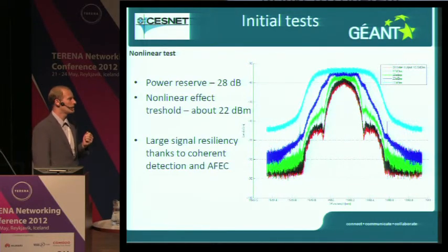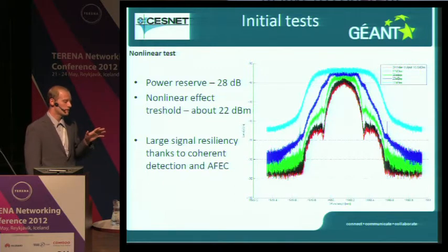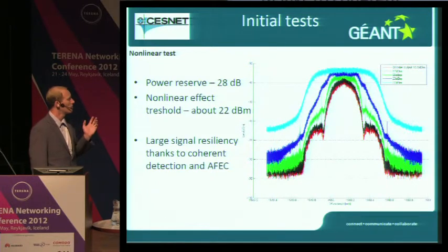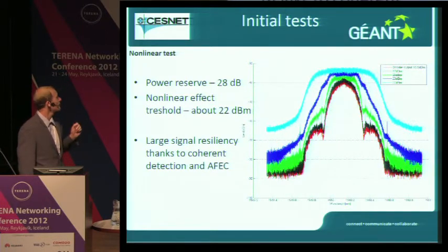That means that the system can overcome a drop in power to almost 1,000th of the intensity, and the coherent detection is still strong enough to decompose the data from the stream and work over that attenuation. Then we looked at the nonlinear effects and some threshold.